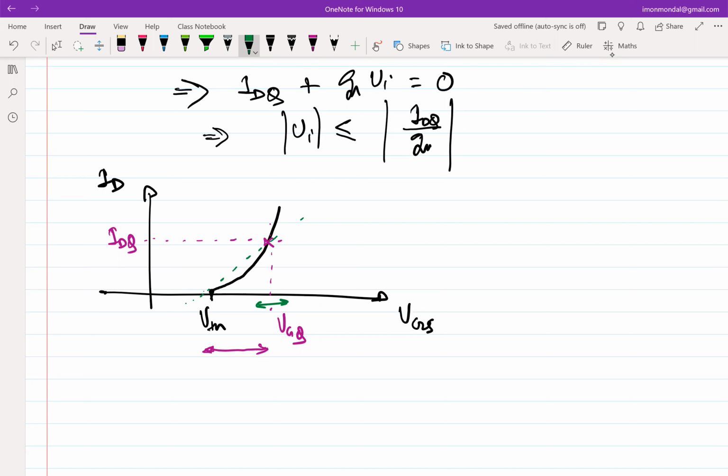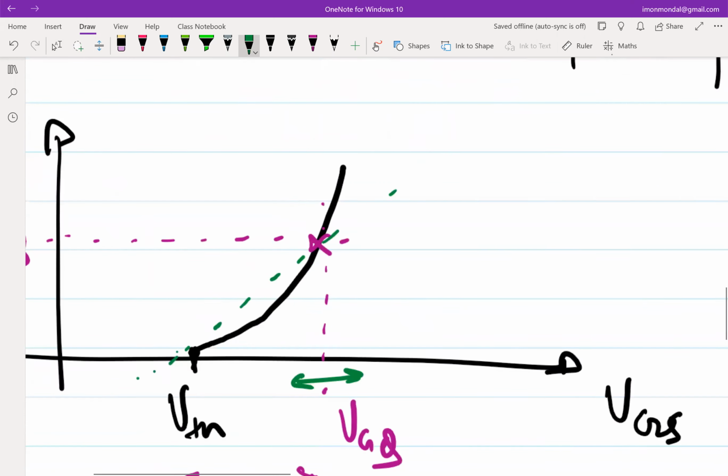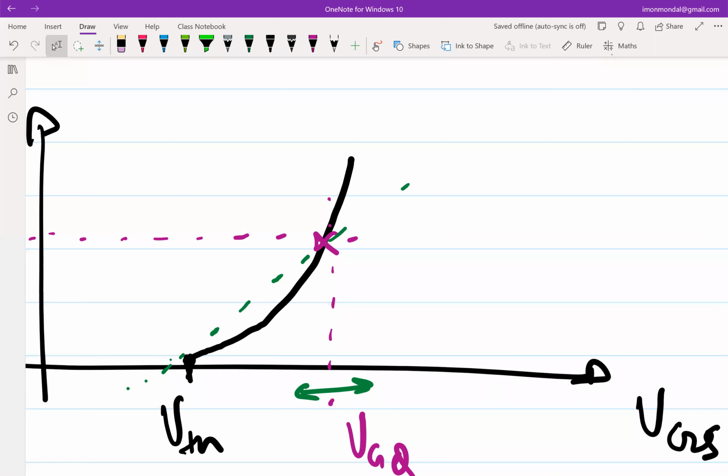Okay, so on the other hand, what are you saying? What I am saying is, instead of setting this total absolute current to zero, I will set the quiescent current plus incremental current to zero, incremental linear current to zero. So what is incremental linear current here? From this slope, how can you figure out what is the incremental linear current? Draw a tangent, right?